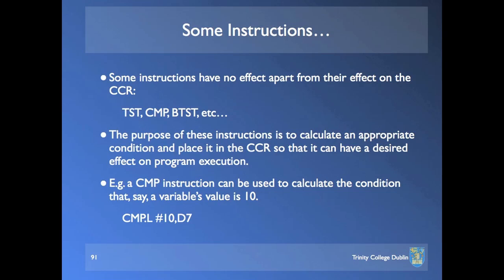Okay? Now it turns out that this instruction here is not needed because this instruction will have already set the condition code register according to the value of the thing that was moved. If the thing that was moved was a byte whose value is 0, the Z bit would have been set here. So we don't need this instruction at all. We can just leave it out. You can omit that instruction. Now, because that instruction is outside a big loop, it's not going to make a hell of a lot of difference. But you might as well remove it. Remove those kind of instructions where you can.